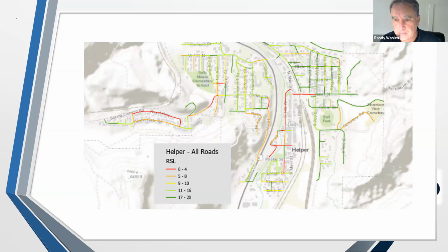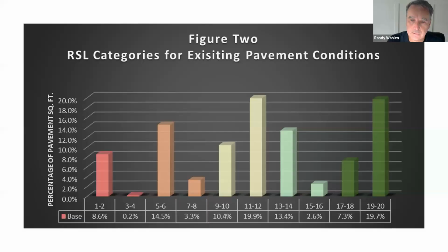Yes, they are already using those, and they're looking at other aspects. They're looking at being able to map all the utility vault locations. One company's looking at using the LiDAR to check retroreflectivity on the signs. Every sign has to have a retroreflective coating that will reflect when the headlights hit it at night. They think they can tune the LiDAR in to rate those signs so they don't have to go out and look at them in the dark or have a special gun to do it. So there are some really interesting advancements in this kind of technology.